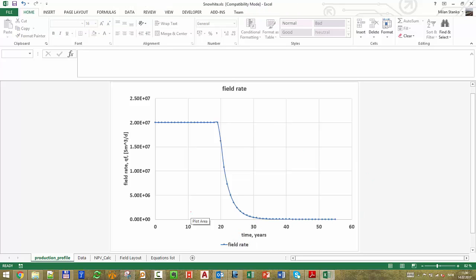Okay, and usually, like I told you, you don't continue all the way until reservoir pressure is the same as the minimum. But you usually use a cutoff value. That's the minimum economical rate that I can get from the field. For oil it is someplace between 5,000 barrels and 3,000 barrels. For gas, I'm not sure, but you have a cutoff.